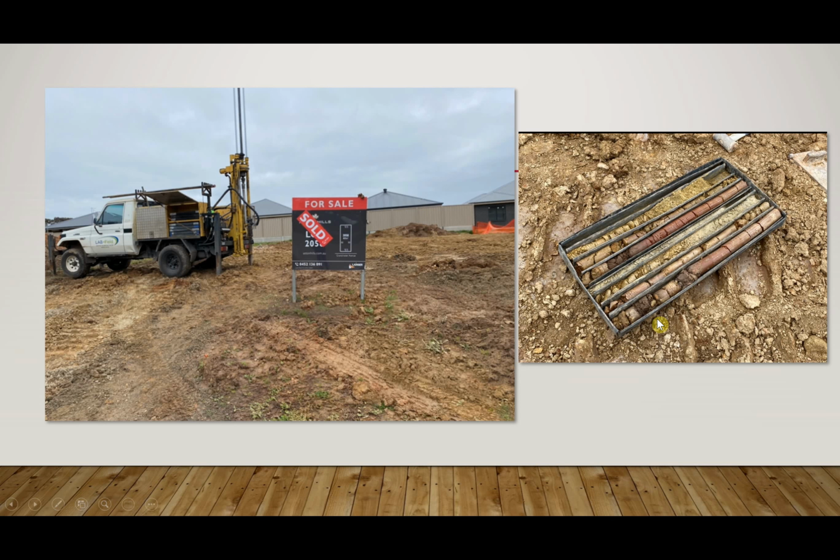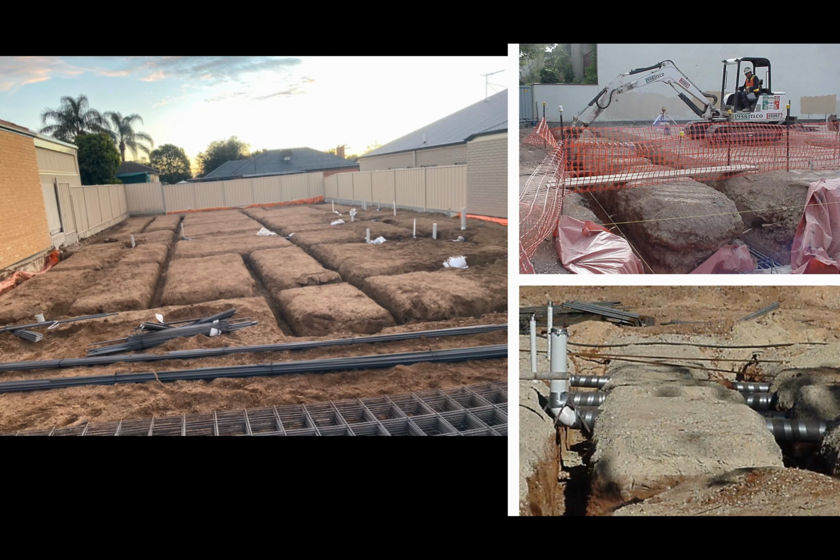So usually what happens is we're looking for here, this is obviously the top of the earth, this here is the end of it. So we're looking through, this here is usually backfill, and this is really what we're interested in. This here, this red brown earth is a clay, and what happens with clays is when water or moisture comes to it, it starts to move a lot more. This here is a bit of a sandy gravel, so it's not too bad, it's not very reactive. But you will learn more of that in your geotechnical class.